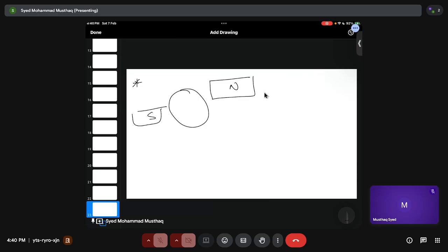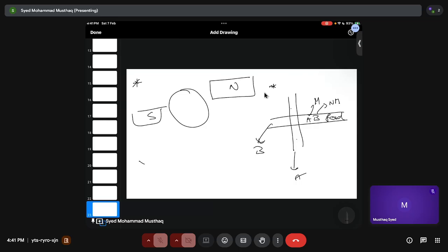That is one thing. And then cross belt. So what do I mean by cross belt? That means one belt carries some feed material. It contains both A and B. So a cross belt is put beside your main feed belt. This belt is magnetic. So let's say A is magnetic, B is not magnetic. A gets attracted to this belt and it flows here. B has no reaction to the magnetic field, so it comes here. So that is about that.